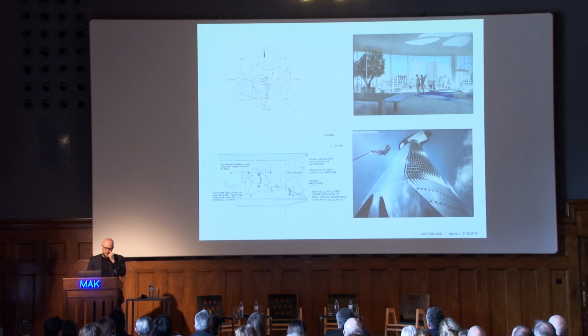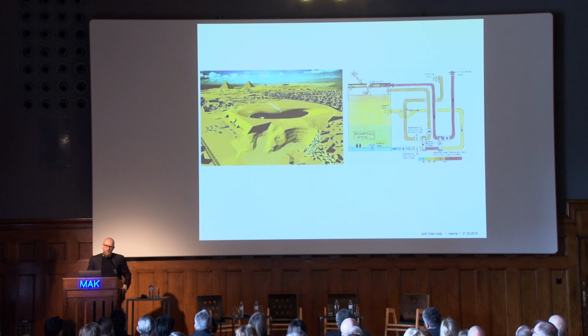Another natural ventilation concept is in New York, where you see on the bottom right the natural ventilation function articulated in the building skin. This is an older project in Giza, Egypt, the Great Egyptian Museum. It is a low-tech solution with a large stone roof made of black stone, which gets really hot in the desert sun. The air from the exhibition space flows through a special construction in this stone roof.